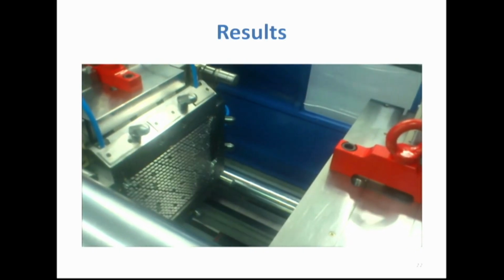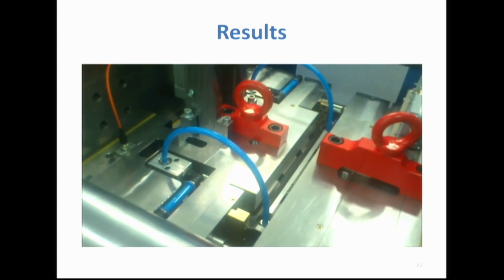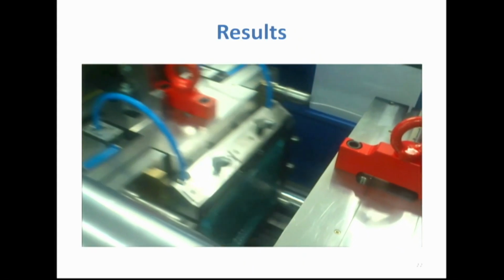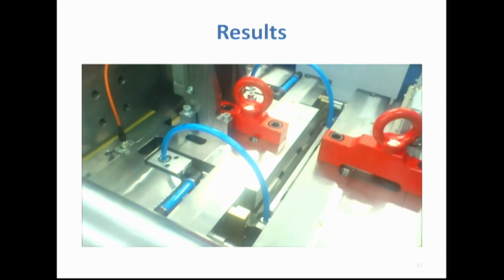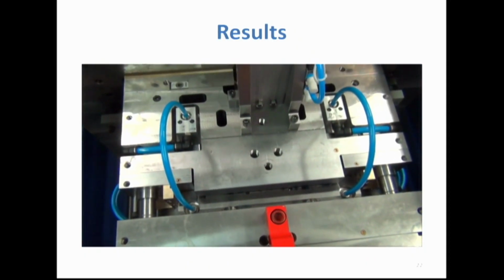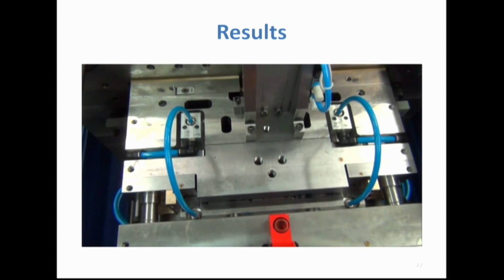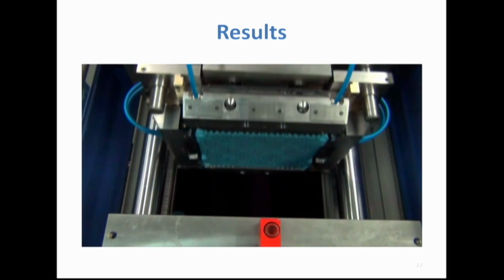And I don't know if you realize that, but most of the molds for mushroom crates have the part oriented in the mold vertically, so the longest wall is put in the vertical way. We put it the opposite way, because then it's easier to drop the parts, and you don't need to open the mold so much compared to the vertical orientation.